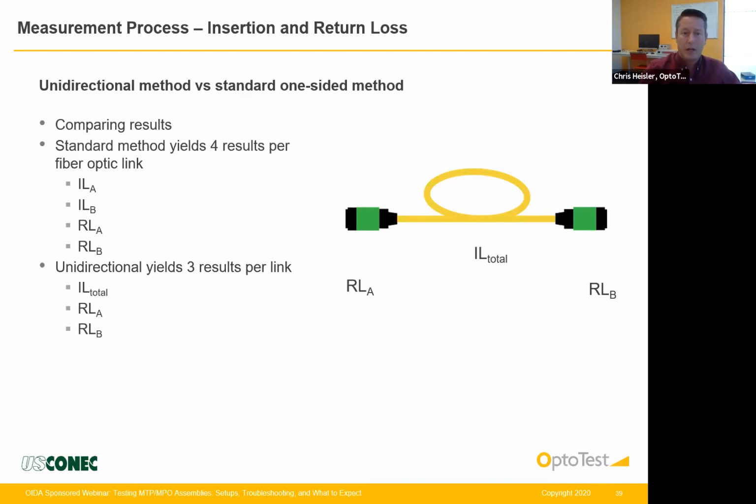So this makes an assembly that should have a normal loss look like it has a very good loss. What's being suggested is to remove those lossy modes on the back end of the DUT. One would connect up a receive cable, and that receive cable could either be standard multi-mode fiber, or it could be bend-insensitive multi-mode fiber that's the same type as the DUT is.